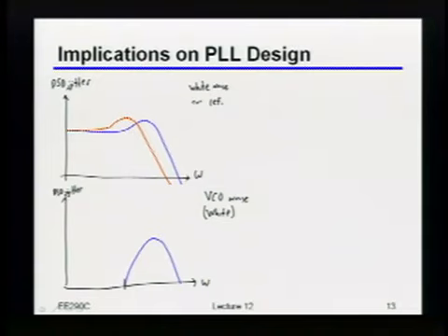Okay, so now what happens when I move to a frequency, let's say I add some nominal frequency, and I move to some other frequency that's twice as high as that? How much gain do I get from the integration in the loop filter? I moved up in frequency. So if I just go through a 1 over S, half. Yeah, I get half the gain, right? So if I have half the gain from my loop filter, that means that noise makes it to the output twice as large, right? Okay, so notice that's why you get this 20 dB per decade on this side, right?